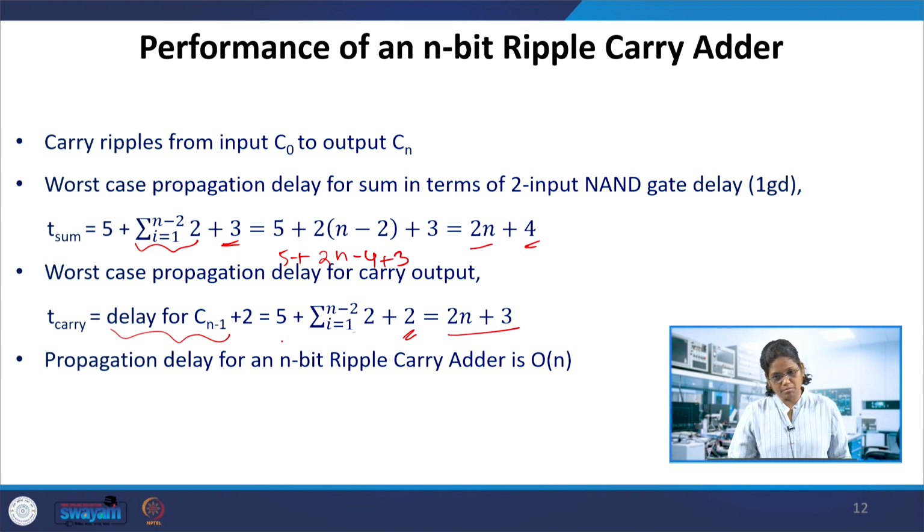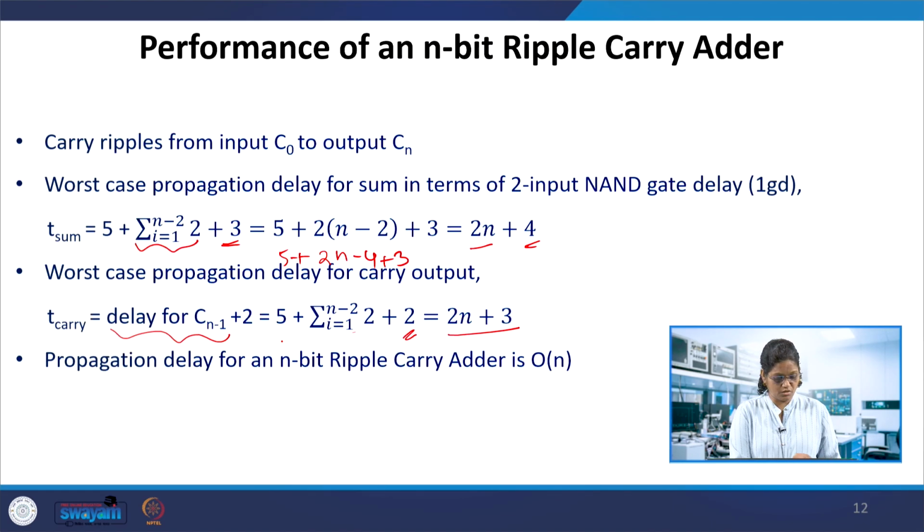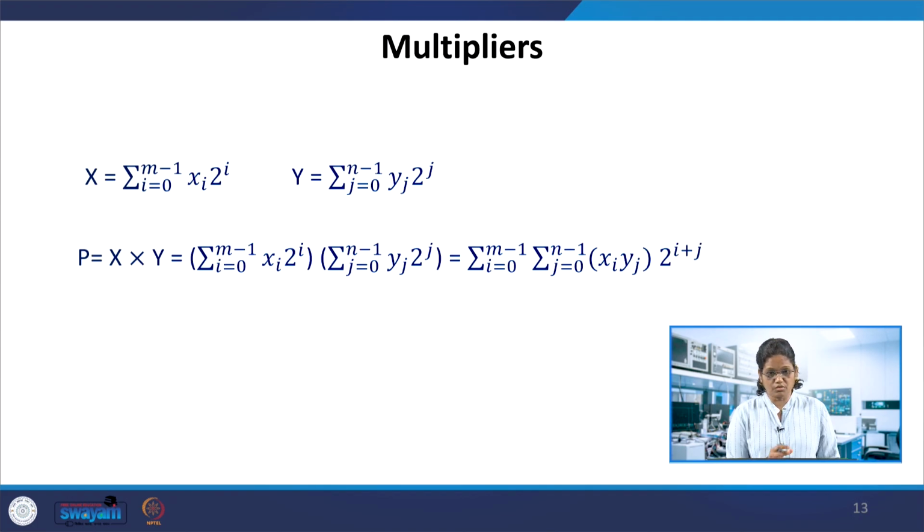If we use this n-bit carry adder, definitely there will be propagation delay in the computation. If we have these adders, the subtractor can also be visualized in that way. For each adding operation, how do we find the maximum here? In this case, it is going to be the worst case delay, which is 2n plus 3. And we'll compute the critical paths using timing analysis for the design. So this worst case delay is involved in the critical path computation.